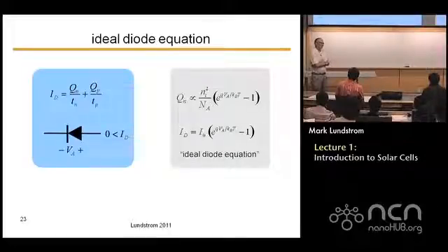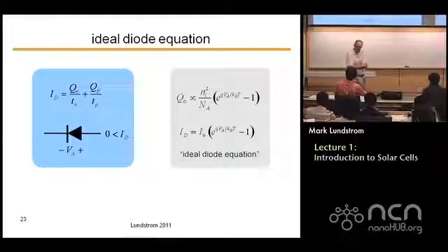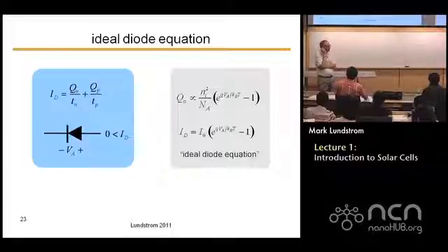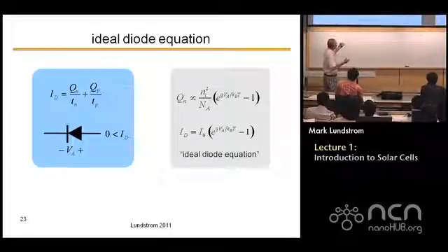Now, there are lots of other non-idealities that we could talk about. Tunneling through defects and things could get very complicated. But you think how much it would really affect our simulations? How much would it be changed? 10%, 5%, or 50%? Oh, no. Especially when you look at these low-cost photovoltaic materials, where you have thin films of polycrystalline material processed at low temperatures, there can be high levels of defects, and there can be many of these non-idealities, and it can be impossible to see an N equals 1 component anywhere. I mean, that can be the whole game.